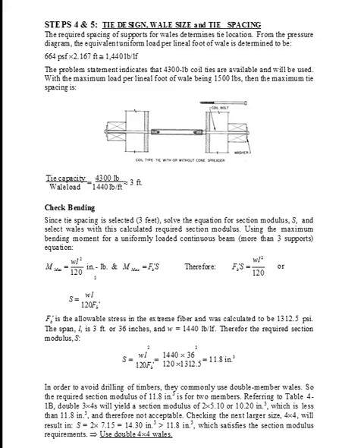Okay, then what you're going to do is look at the tie design and the tie spacing. Again, ties cost money, and they help maintain the dimensional integrity of the forms. So it's important that you look at the spacing, and if they're spaced too far, again, that's where you get bending, right?